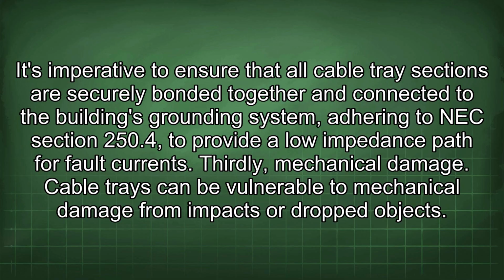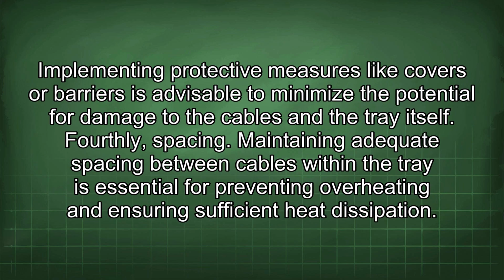Thirdly, mechanical damage. Cable trays can be vulnerable to mechanical damage from impacts or dropped objects. Implementing protective measures like covers or barriers is advisable to minimize the potential for damage to the cables and the tray itself. Fourthly, spacing. Maintaining adequate spacing between cables within the tray is essential for preventing overheating and ensuring sufficient